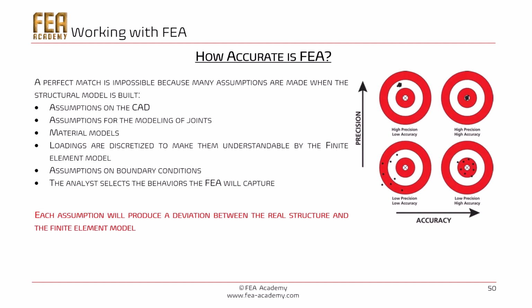For steel structure, this error is very small since there is less than 1% variation in the modulus of elasticity of steel. However, when analyzing soil, for example, the error in material response could easily be 20%. The largest error in most FEAs is the result of bad boundary conditions. Incorrectly supporting your model can result in large errors that are transparent to the user.